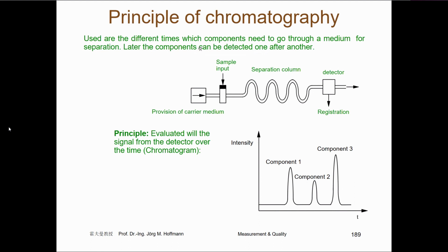When you now have a mix of gases and you have the detection of a component after this time, what you have detected for CO2, then you know that is CO2 in this mix. And so you get over the time the different components in the gas. When you would like to know what it is, you have at first to calibrate.